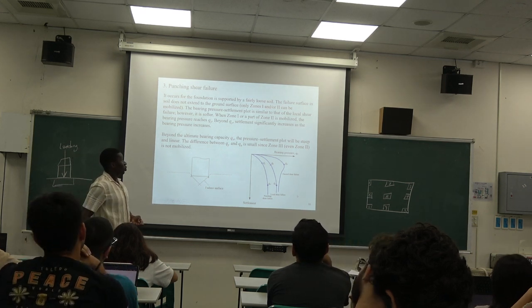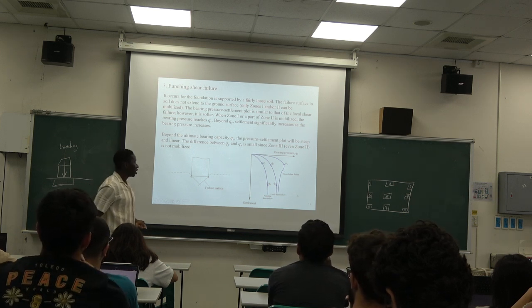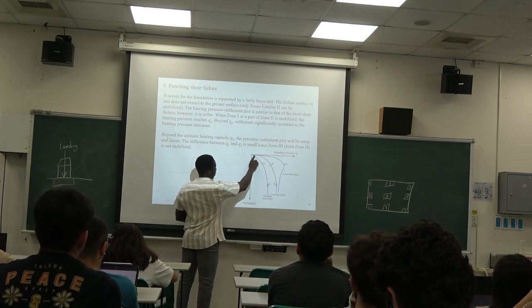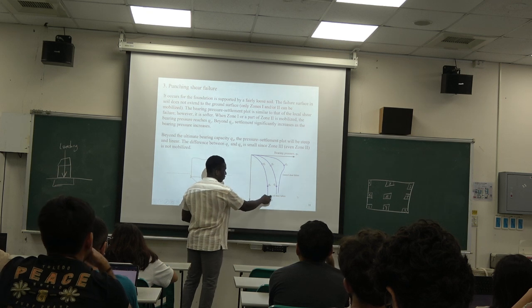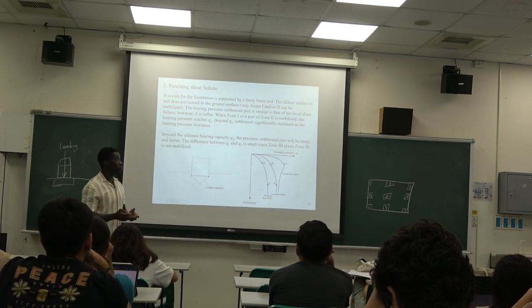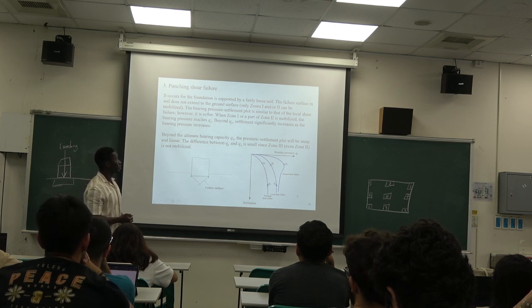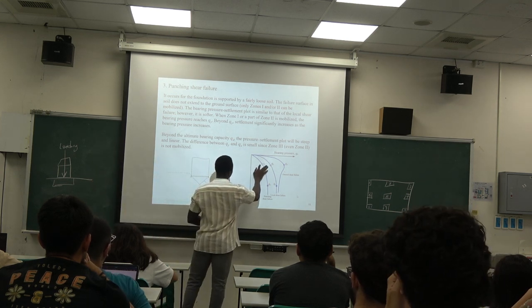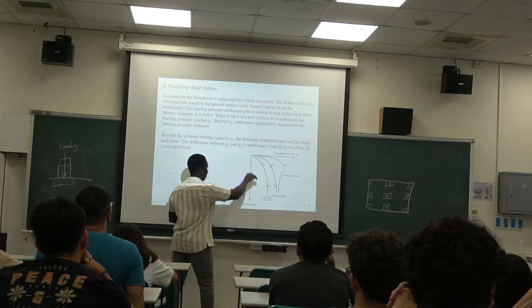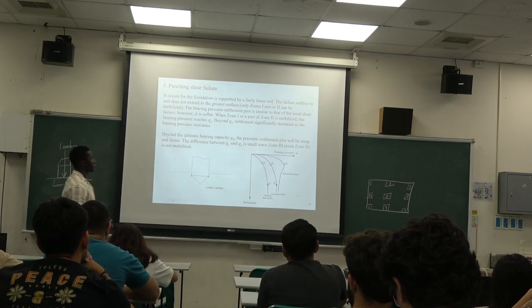The bearing pressure settlement plot is similar to that of the local shear failure, however, it is softer. Okay? So you can see it doesn't take much bearing pressure compared to the local shear failure for you to have punching failure, because you are dealing with much softer or loose soil. And then it's the same thing. Once it reaches this yield point, the settlement just significantly increases.